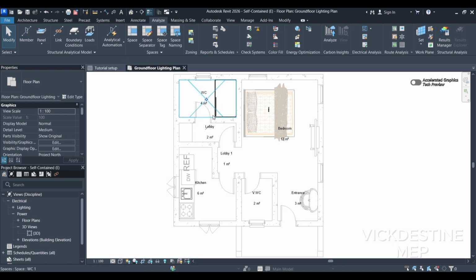So in order to have your lighting in, okay, let's just assume we have families already imported in this project. How do you bring them into your plan? Okay, so let's say this is a floor plan. This is a floor plan. So we want to open ceiling plan. Okay, remember the naming we did in the previous tutorial was just for the floor plan.